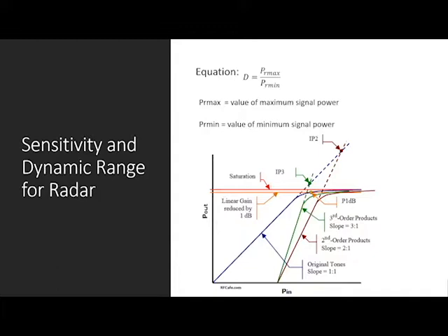The third order intercept point of a receiver, mixer or amplifier is a mathematical concept. It relates the nonlinear products of the third order nonlinear term of a Taylor series expansion to the linear output signal of a component such as a mixer or amplifier. In some cases, a component's linearity may also be defined by its second order intercept point, which uses second order terms of a Taylor series expansion.